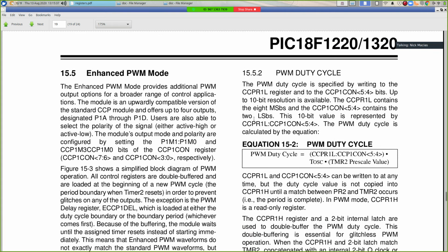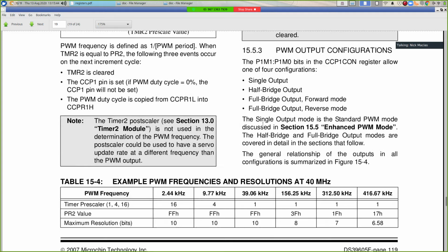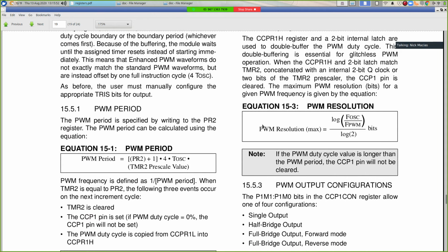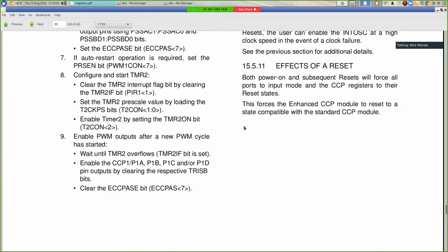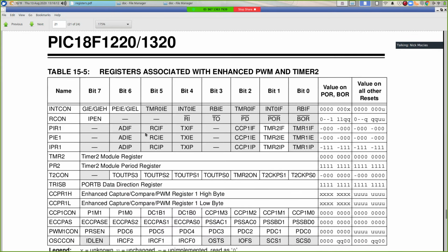We're not going to play with this in this class. Normally we use these to actually drive around a little car with variable speed. But if you do embedded systems down the road, you'll definitely encounter this, and I just want you to know that there is a system inside the chip for actually generating these pulse width modulated signals. And when you set this up, it's a simple 9-step process.